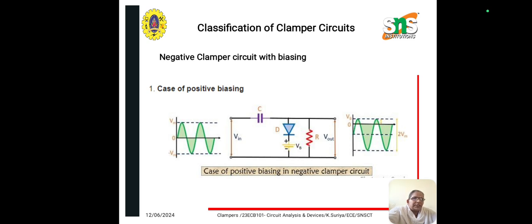When positive half cycle of the AC signal is applied, the diode is in the forward biased state due to the AC supply but is reverse biased because of the battery voltage. So the diode conducts when AC supply surpasses the battery voltage. When we apply negative half, the diode is reverse biased by the cause of the AC supply and the battery voltage. So this non-conducting state of the diode discharges the capacitor. Thus the voltage across the capacitor applies at the output.